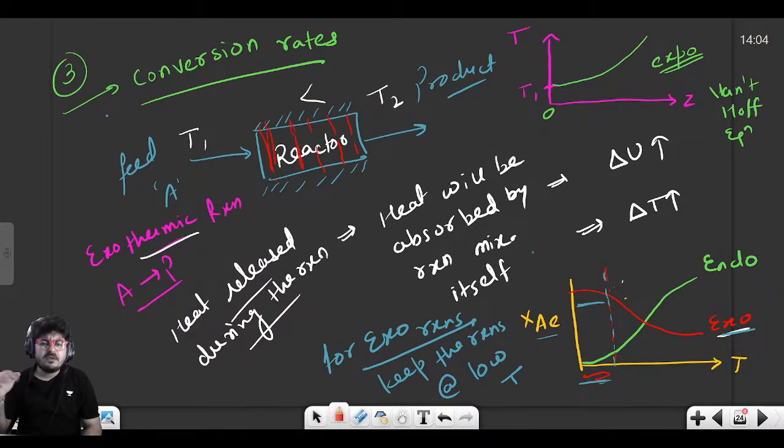So you know that here, one more point, if you wish, you can add about the catalyst. Okay, due to the temperature gradients, catalysts can also get affected. Unwanted reactions may start, and the catalyst may degrade. Or it is possible that fouling starts on the catalyst, basically catalyst deactivation. So many things are there.